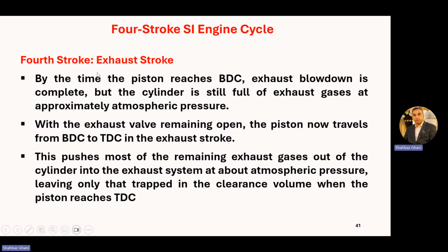Now the exhaust stroke, the fourth stroke. By the time the piston reaches BDC, exhaust blowdown is complete, but the cylinder is still full of exhaust gases at approximately atmospheric pressure. The cylinder is filled with exhaust gases and the pressure is still high, approximately atmospheric pressure, but still high. With the exhaust valve remaining open, the piston now travels from BDC to TDC in the exhaust stroke.